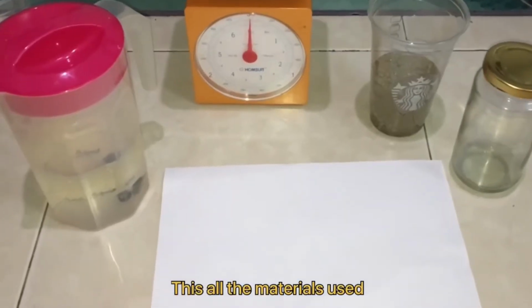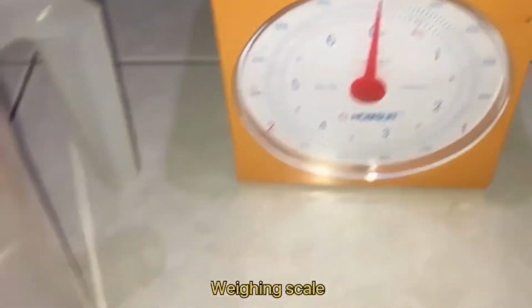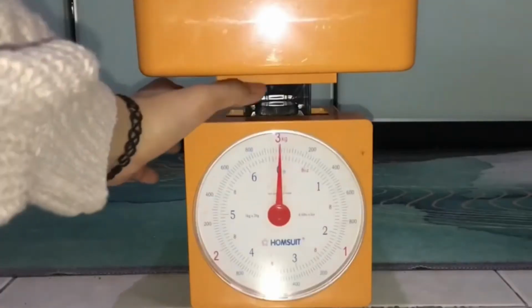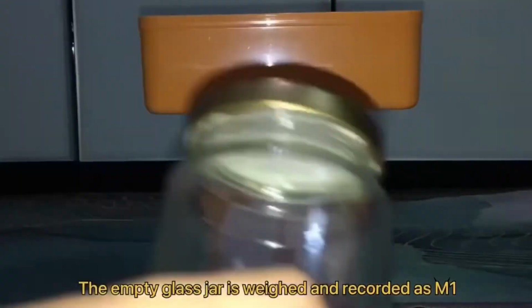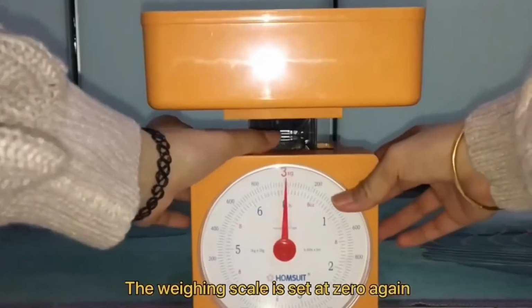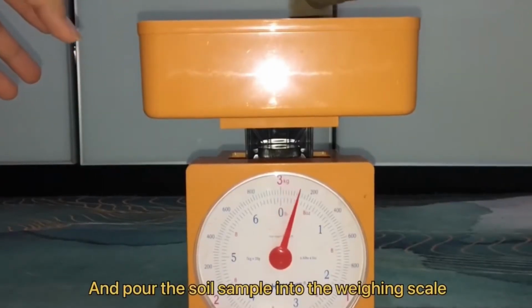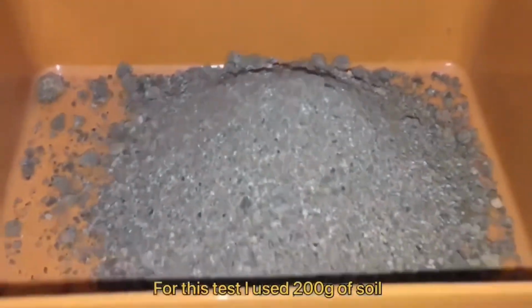This is all the material used: a glass jar, a soil sample, weighing scale, a jug of water. First, set the weighing scale at 0 to avoid error. The empty glass jar is weighed and recorded as M1. The weighing scale is set at 0 again, and pour the soil sample into the weighing scale. For this test, I use 200 grams of soil.